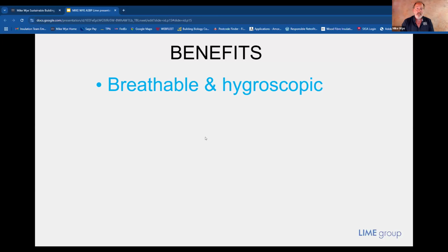Cement has some similarities to hydraulic lime in essence in terms of the origins of the raw materials, but there are differences in production. Cement is produced at much higher firing temperatures, for example, and the end result with cement is a hydraulic binder used to make mortars and other materials, concrete for example, which by nature produces a very, very hard and robust end result, but at the same time it also is less breathable, it's less vapor permeable. There are some jobs cement does so well that it's hard to find an alternative.